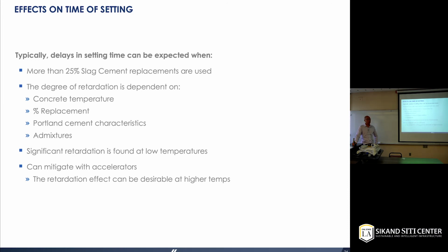When you're doing construction at a very high replacement rate and at very low temperature, we usually recommend adding some accelerators to your concrete mix to ensure you have time for cutting the joints and make sure the concrete hardens at the right time.